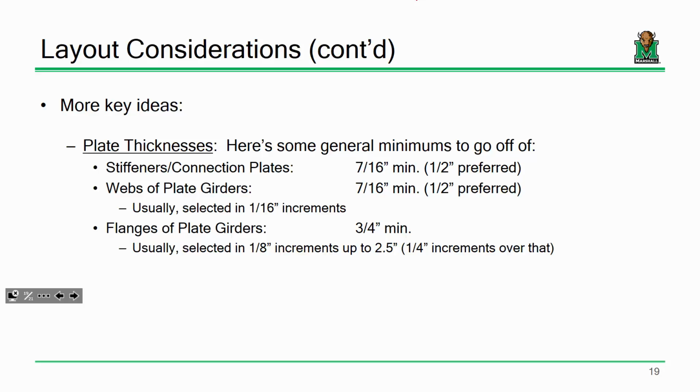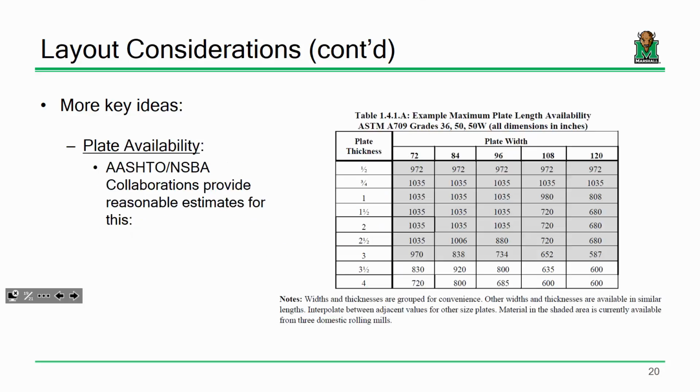It's pretty floppy, and you've got to take this and weld it to other sections, and it's got to maintain its shape. It gets tough to handle if you use really, really thin sections, even if the math works out and the capacity's there. So there's a little bit more to it than just the math. You've got to think with a little bit of common sense in terms of the sizing. Everybody okay with that? Okay.